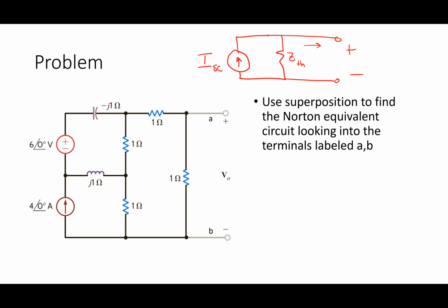This guy is entirely equivalent to a Thevenin equivalent. And you see the source transformation would tell you that, right? You would see that the source transformation would tell you that ISC times Z Thevenin is V open circuit. That Z Thevenin, I've talked about this a lot now. That Z Thevenin, that's the impedance that's seen by what source?